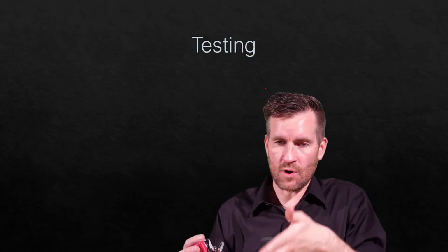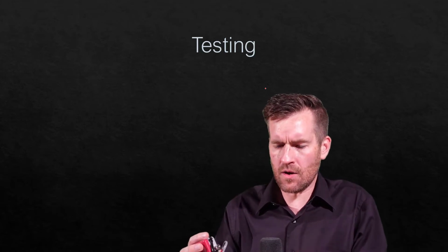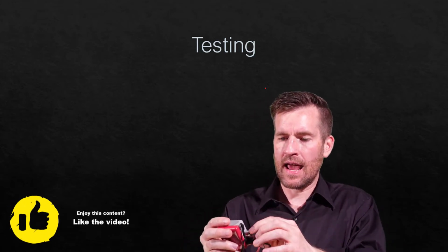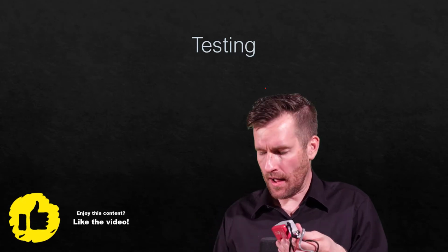But it can sometimes be hard, if it's not properly labeled, to know which line is associated with that jack. So if you're trying to make that jack live and figure out where it goes, what you can do is plug this RJ45 into the end of it, and then I can click this to generate a tone. And it's going to generate a tone on that line.